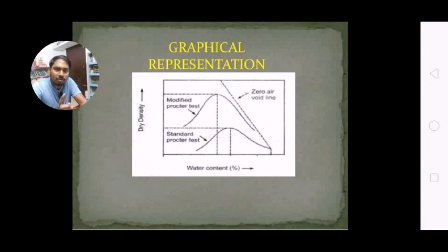In case of consolidation, it is very important that the soil should be saturated, but this condition does not apply to compaction. Compaction is possible in saturated soil or partially saturated soil; that doesn't have any effect on the compaction of the soil.